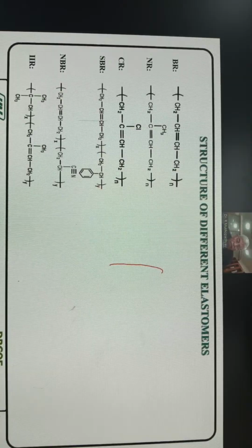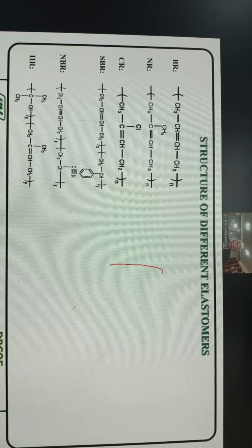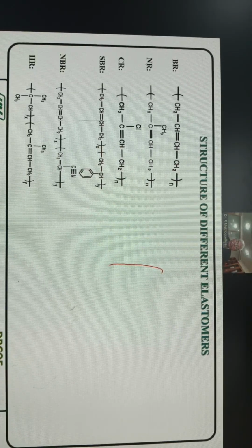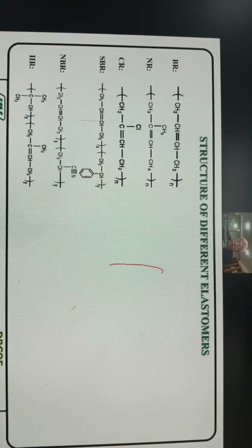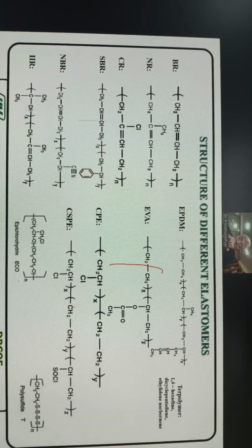In the case of SBR, sulfur has to be reduced and accelerator increased to speed up and enhance the cure rate. Similarly, the compounder must know what cross-linking agent to use and what the sulfur accelerator ratio should be.